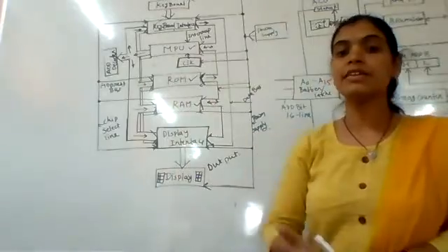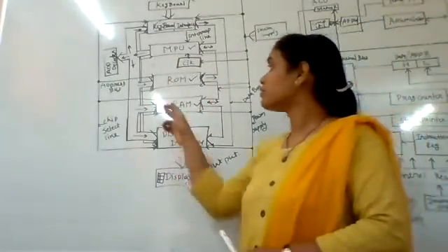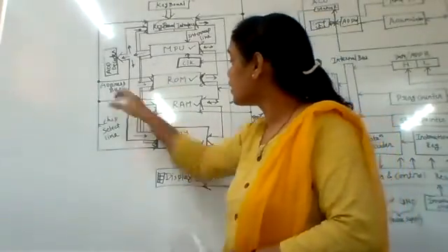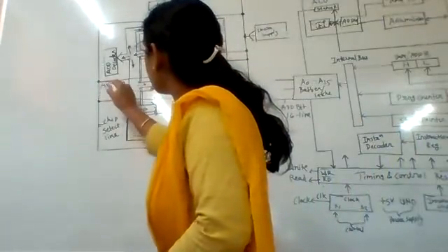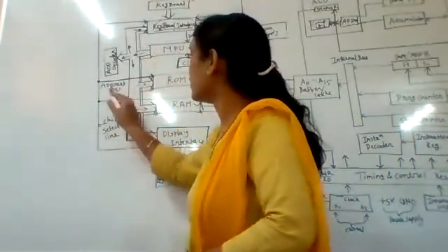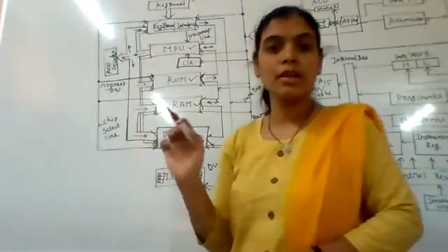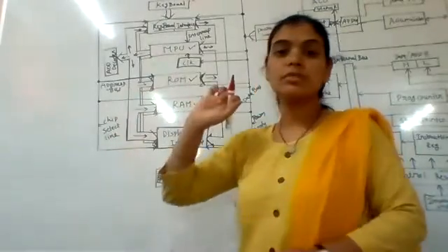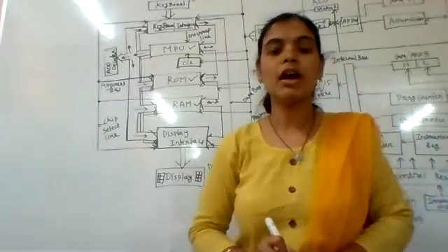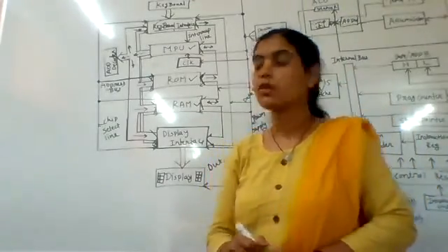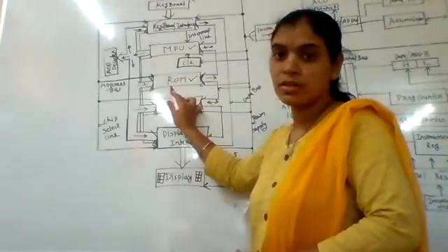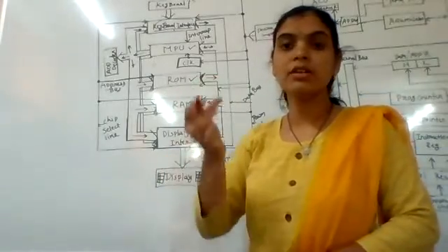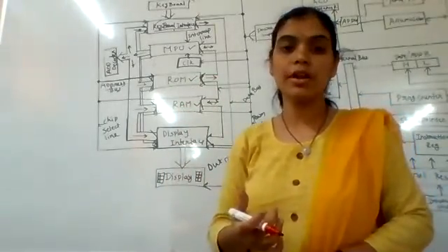It has an address bus, chip select and signal lines. The address bus is connected here. It has a chip select line and signal lines also. It allows only reading of stored information. This is unidirectional. Data flows in only one direction. It only reads stored information.